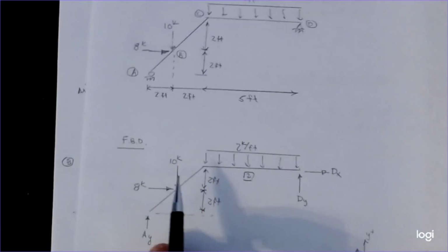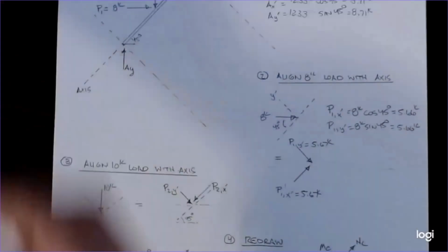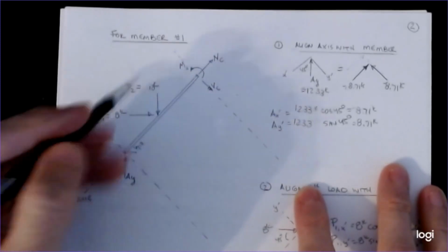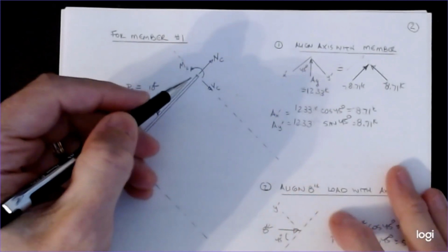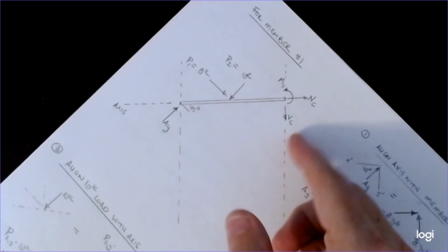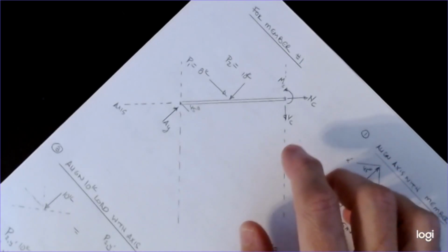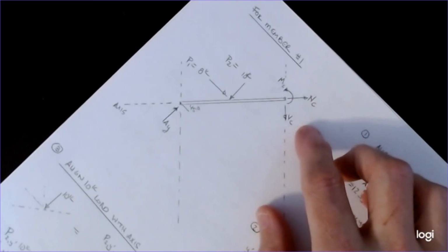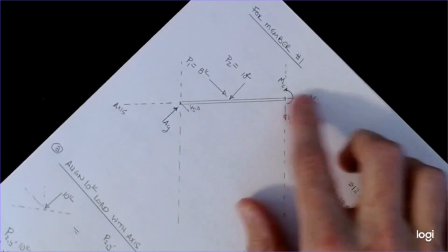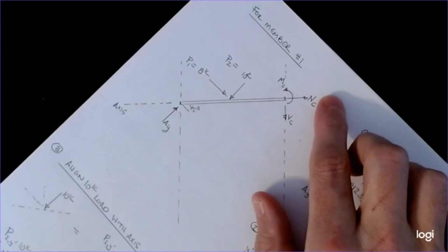So we're going to cut this diagonal member off of the structure. And when I do that, you end up with a free body diagram that looks something kind of like this. Again, I've left it at its inclined orientation and put all the stuff that I know. I basically cut this thing off just before the joint at C. And if I turn my paper that way, it now starts to look a lot like everything that we've done before. This is my positive sign convention for a cut on the right side, if you remember back in the video. If you don't remember that, go back and look at that in one of the earlier videos. And so VC is acting down. MC is counterclockwise positive, which is what we expect. And NC is a tensile load, which is considered positive on our sign convention. So those are our unknowns.